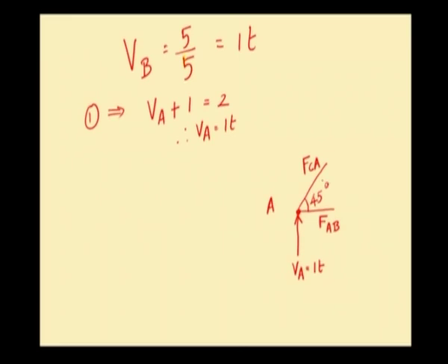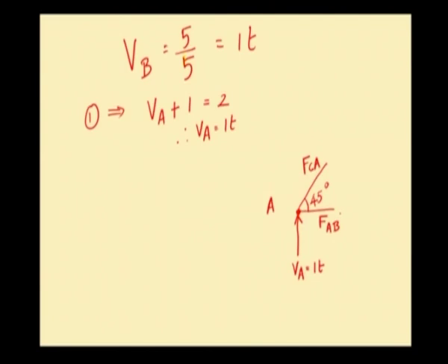Now, these two members AC and AB may be subjected to any nature of stress, that is, it can be subjected to either tensile force or compressive force. Generally, all bottom chord members of the truss will be subjected to tensile force. As we have seen earlier, tensile force will be indicated by an arrow mark pointing away from the joint.